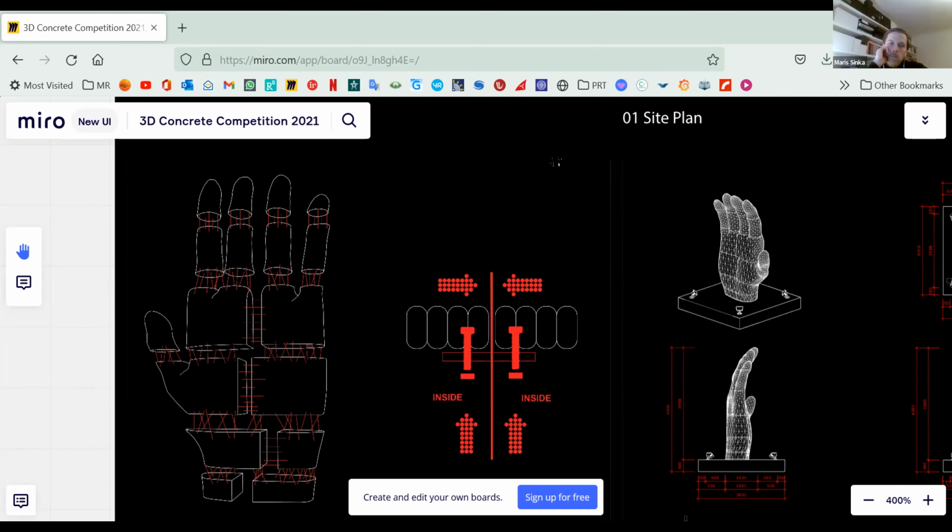connections for the bolts. And also what Fabian said last meeting, that if we have, for example, here that you can see the hand splits in two and there's a straight edge between, so a straight surface, the connection points wouldn't be straight because the printer can't print 90-degree edges. So the hand would have these edges with curvature in. This is not the best place, because you would print like this, and then you would stop here, and then this definitely will not be straight.